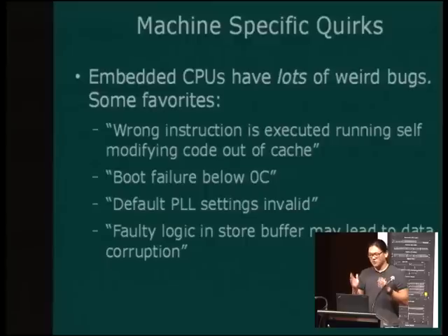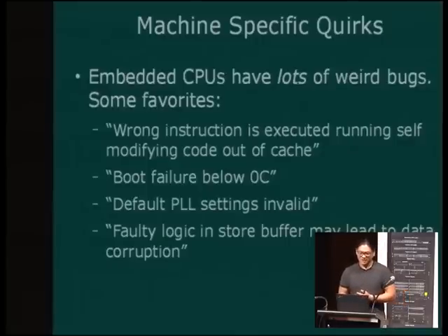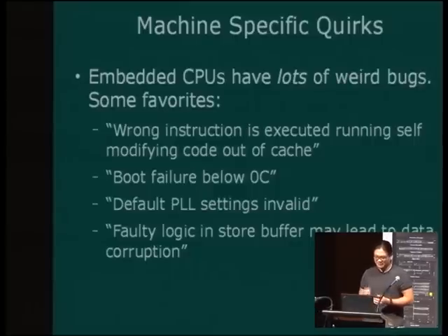It would cause the PLL to be unstable and jitter way beyond spec. And so after running for maybe a week, maybe about 3 days, sometimes as short as a few minutes, systems would lock up, right? And these kinds of things are incredibly hard to figure out. It's very subtle, and eventually we figured that out and had to put a fix in the bootloader to correct the PLL settings.